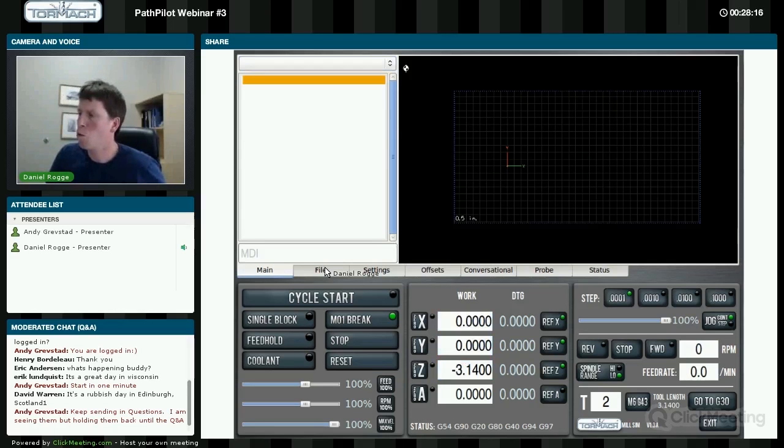On the right lower third of the screen here, we have manual controls. That's step increment here, jog percentage, spindle forward and reverse, and an RPM DRO, feed rate DRO, spindle range button, tool change, and go to tool change position button. So that's the persistent controls.